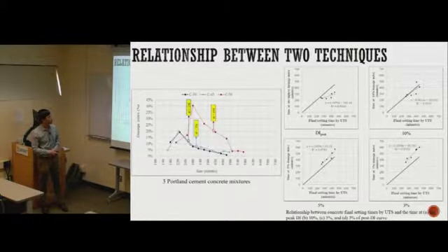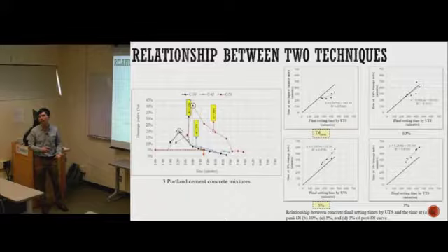Here I found the time that we had the peak damage, which is this peak, the time that we had the highest raveling damage. And I correlate it with different times of, like, 10%, 5%, or 3%. 5% means the time that the concrete has a 5% raveling damage index.